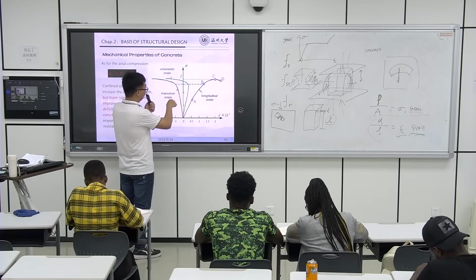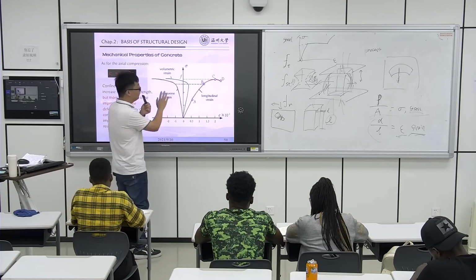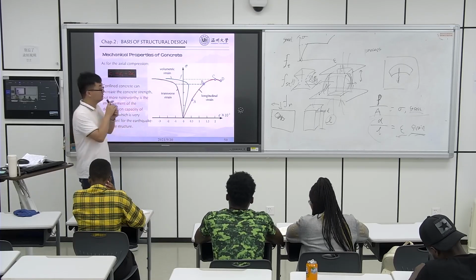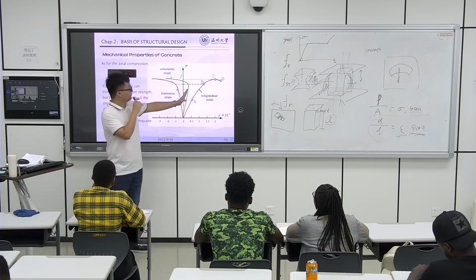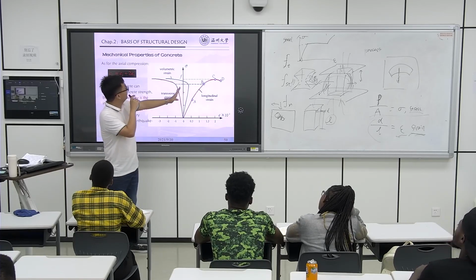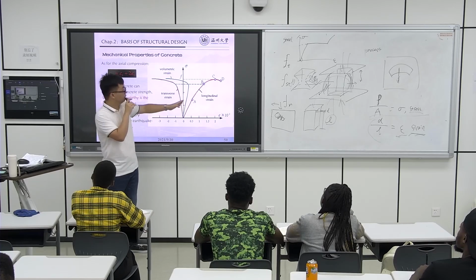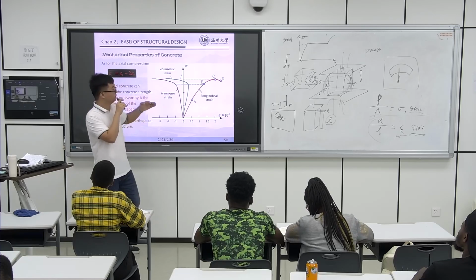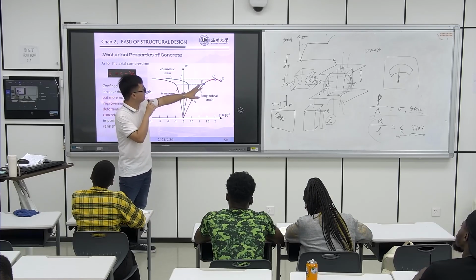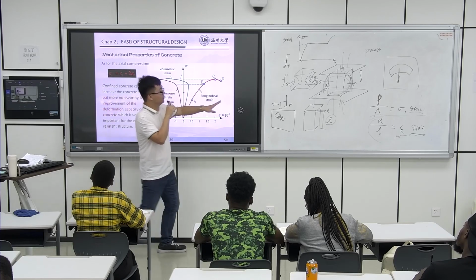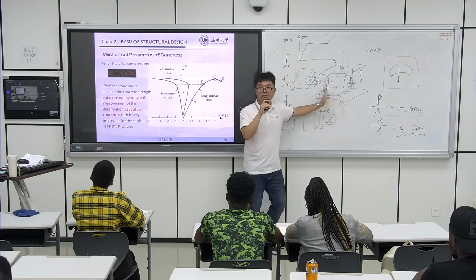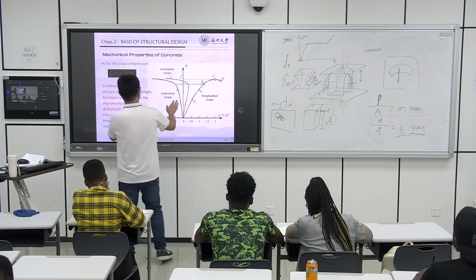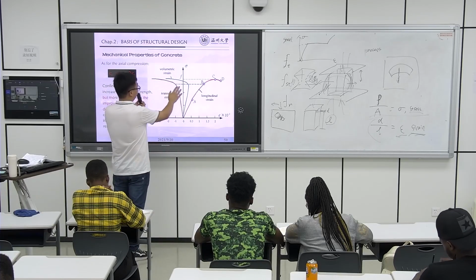In one side the transverse strain is smaller than the longitudinal strain, but with the two sides together, the volumetric strain increases from this curve. Okay, and later in the third period, it increased, but some concrete peeled out, peeled from the concrete cube. So the volumetric strain decreases.